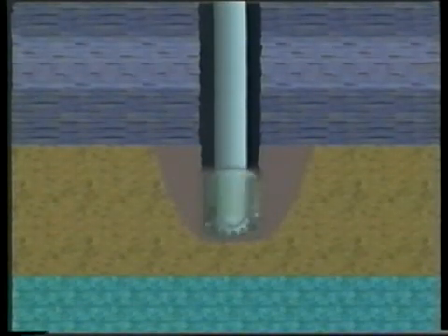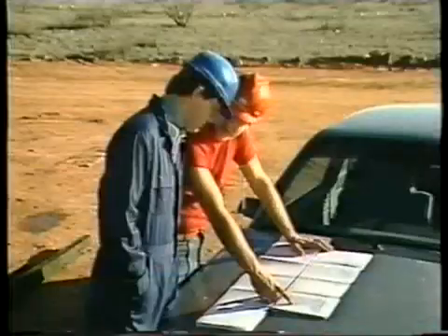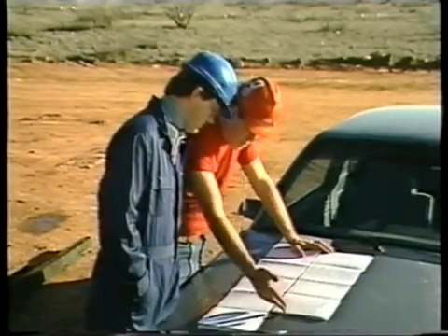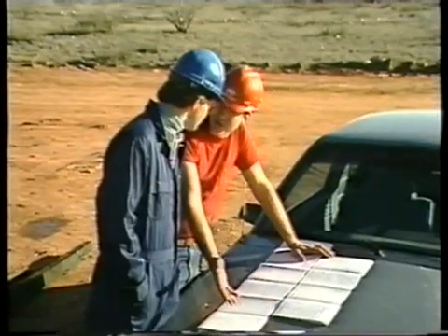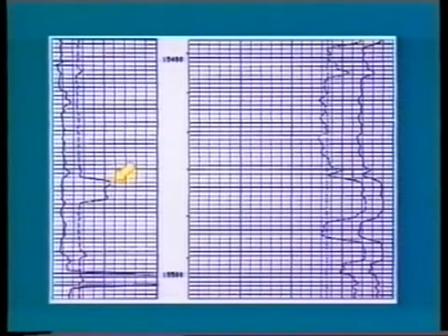For example, if drilling mud filtrate penetrates a formation easily, a logging tool sensing this effect could be qualitatively indicating good permeability. In other cases, the effects of drilling with regard to log evaluation can be detrimental. For example, when the drilling process has created an irregular borehole, or the filtrate has penetrated deep into the formation, some logging measurements can be erratic, insensitive, or difficult to interpret.